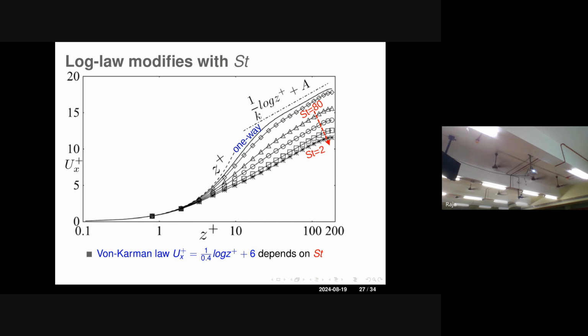Because of that, from a simulation point of view, to justify the particle, whatever one is considering, it is supposed to be way smaller than your computational mesh. And second, you need to integrate it, because it's not just one particle involved. Your velocity field needs to be integrated, resolved, distributed onto these points. But if your particle itself is of that size, how to do that is the next question for Lagrangian point particle density.